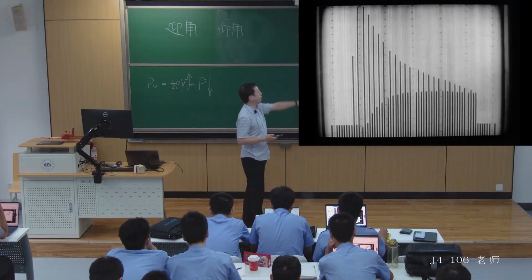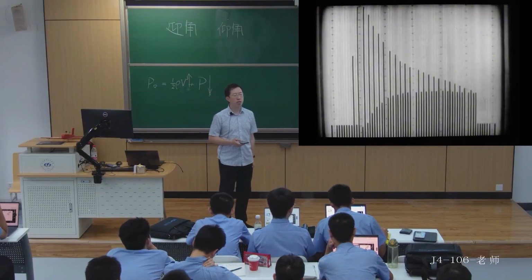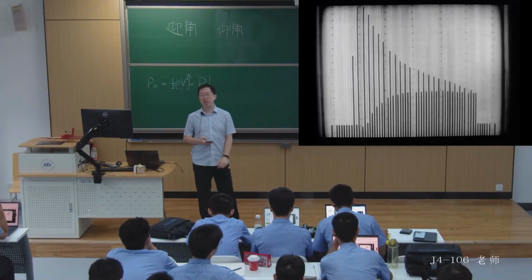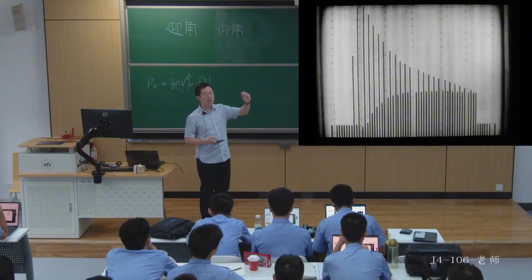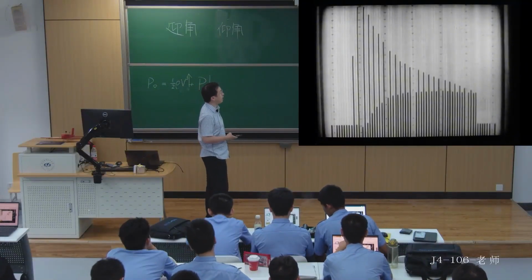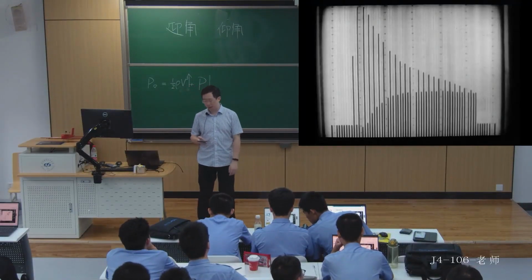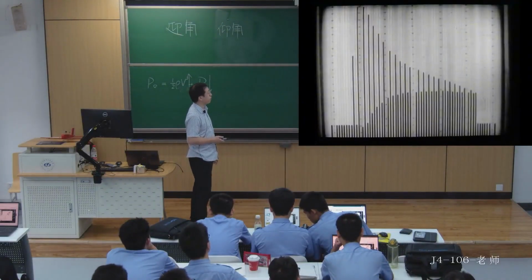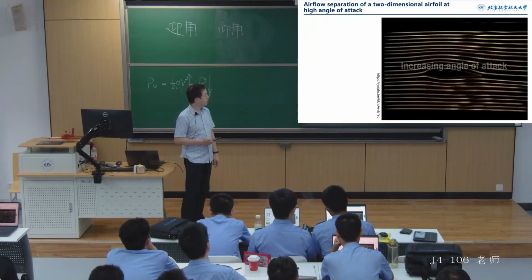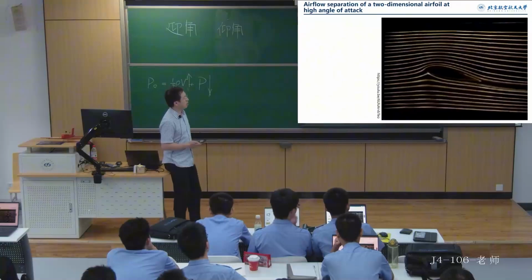So, besides using this method to observe changes in lift, we can also use the smoke wind tunnel setup to see how lift generally changes with variations in the angle of attack. By observing the smoke trails generated by the smoke generator, we can qualitatively analyze the flow behavior to some extent. Let's take a look at how the smoke trails change as the angle of attack varies. We can see that when the angle of attack is small, the smoke trails flow closely along the contoured surface.